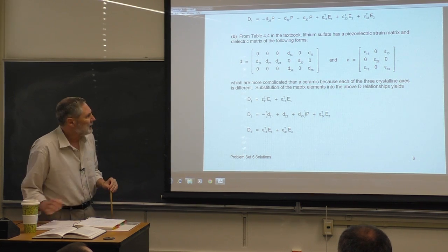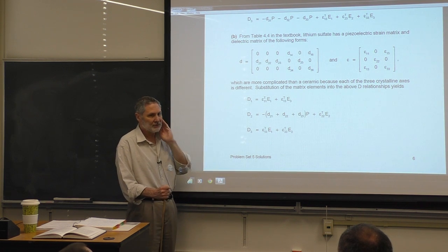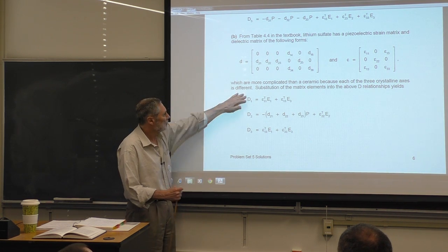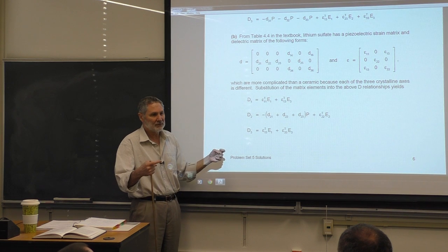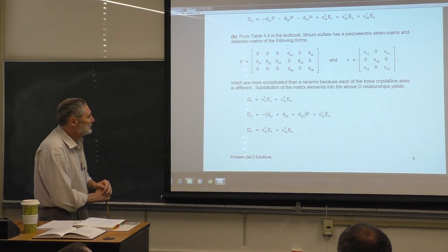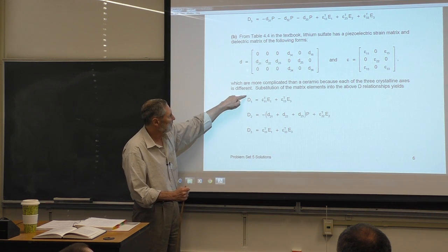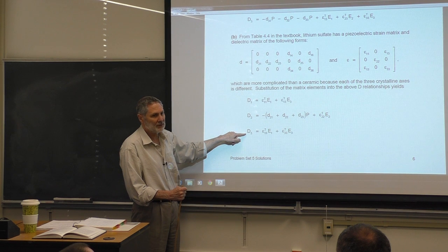Okay? Because it's a hydrophone, all the D's will be 0. There'll be no free charge, or extremely little, negligible. So all the D's have to be 0, no matter what you're picking up, what pole faces you're picking up on. So I want you to focus your attention on the first and the third equations here. We have zeros here, right?